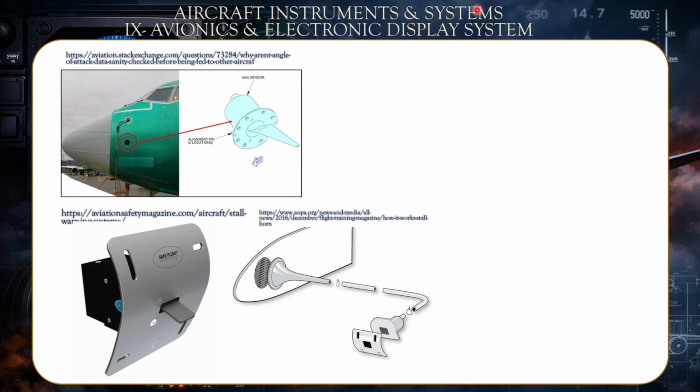Now, to the top left of this slide, we observe the illustration of the AOA sensor. AOA, of course, stands for the angle of attack. And this type of sensor works by measuring the shift in the capacitance value of this inner part of the sensor that would be on the inside of the aircraft, and the part sticking to the outside is the rudder-like winglet that would change direction based on the airstream or the airflow.